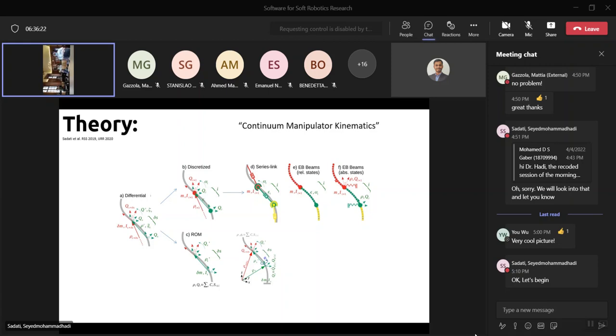I noted that getting the tangent frame and the real material frame, enforcing that by the constitutive law, is not accurate enough. So recently we developed a specific Bishop frame to guarantee that tangency and the correctness of capturing the material frame. And recently, Federico Renda's team have developed a similar method, but instead of capturing the system geometry, they went for capturing the strains and torsion with these reduced order models.